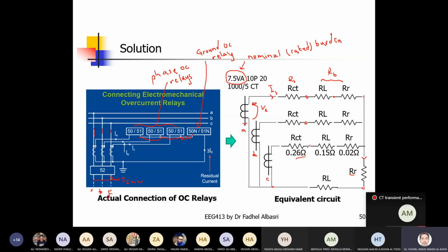The advantage of comparing VS, the actual secondary voltage, with the voltage class, my limit at the secondary, is that I even include the voltage drop at the CT. So that's more accurate than comparing just the voltage at the burden. All right. Any more questions?